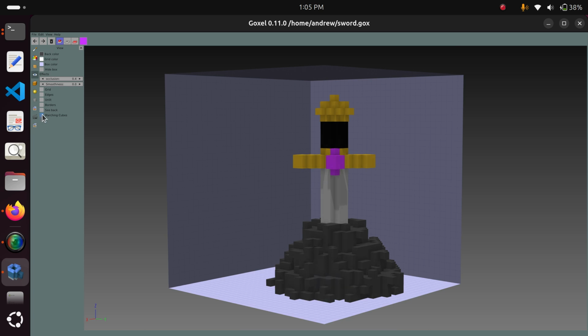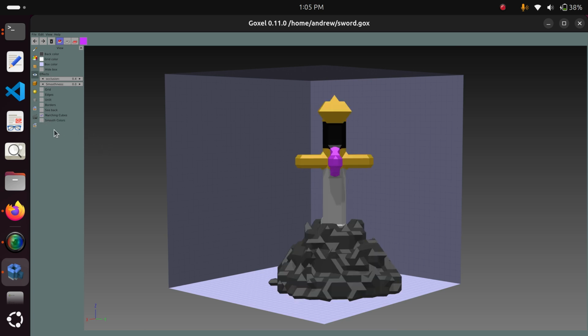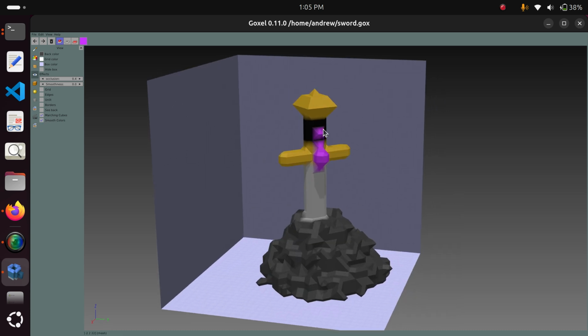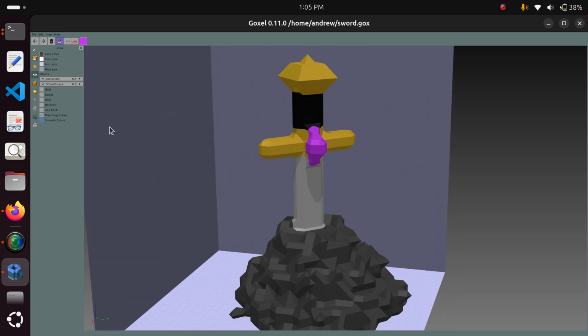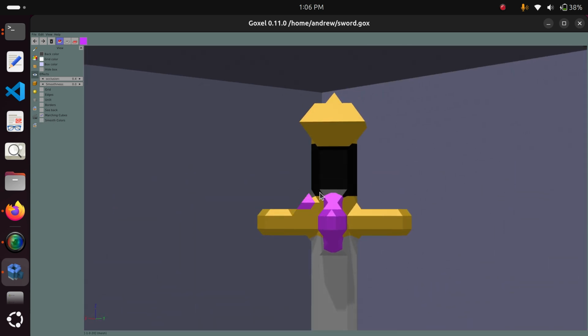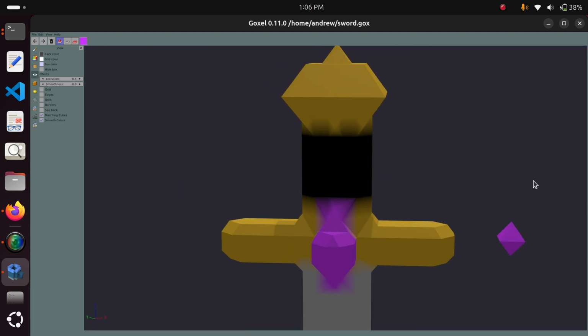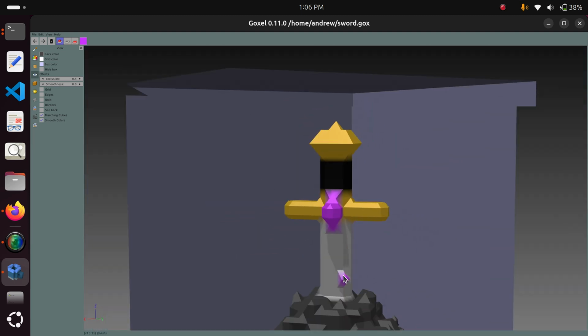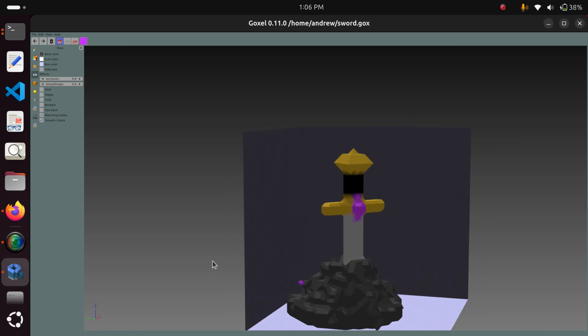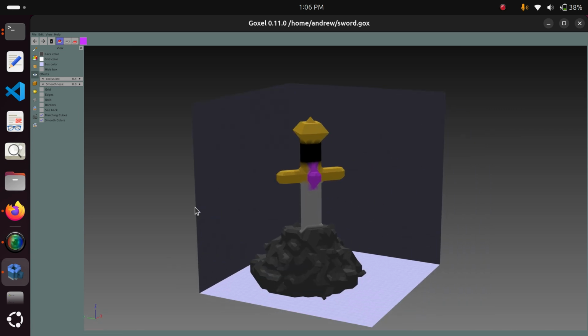And besides marching cubes, there's also this feature to make the color smooth, and you check it. It's only an option once you've checked marching cubes. So after you've checked marching cubes, you can try it, and it will just make the colors mesh a little bit better, right? Do you see that before they were very restricted? And now when you click smooth colors, they kind of blend in with the other colors. And that gives it a little bit more of a realistic feel also. Okay, so I'm gonna save it as is.